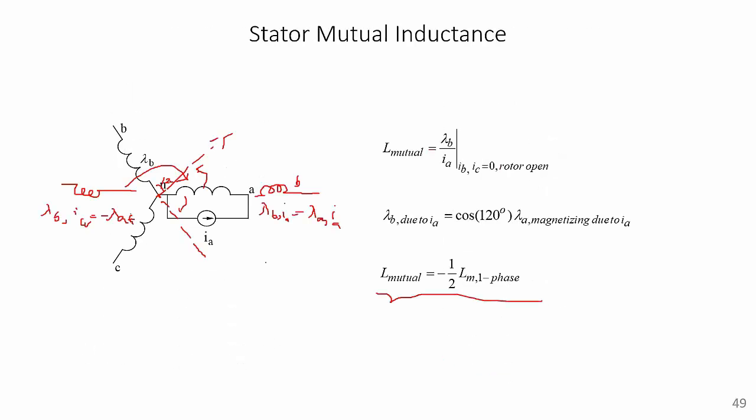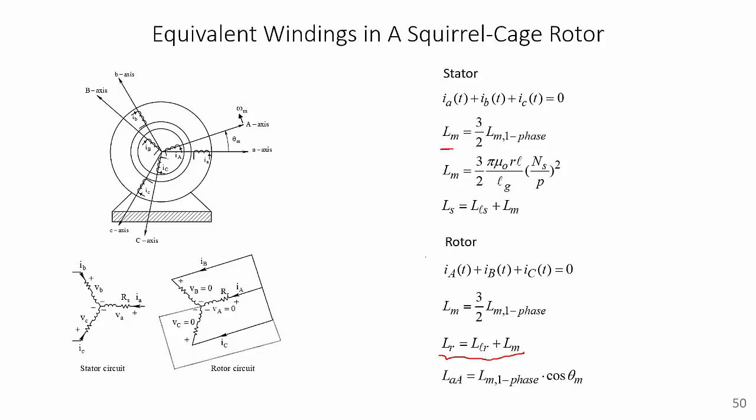In the case of stator to stator winding linkage, the windings were fixed and not rotating, thus the angle of separation between the two phase windings was always a constant. But in case of interaction between the stator and the rotor windings, the angle is continuously changing as the rotor rotates, and thus the coupling between the two windings changes as a function of the angle between the two windings. So having established the inductances of the motor, the only other component that remains is the rotor resistances. And these, unlike the inductances, are not a function of the rotor position or the winding distribution.